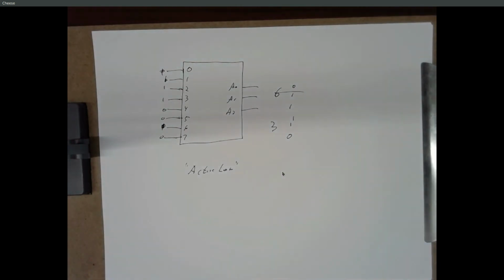And this is potentially a can of worms. We always think of 1 as being a thing, right? When something is 1, it's on, it's true, it's happening. That's just an arbitrary convention. And we could just as easily say that when this thing has input for me, that data available signal is going to be a 0, and when there's no data, it's going to be a 1. Perfectly fine convention. It's just not what we normally do. But that would be called active low. So a 1 would be off and a 0 would be on, basically.